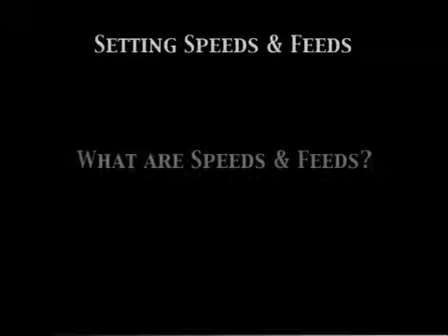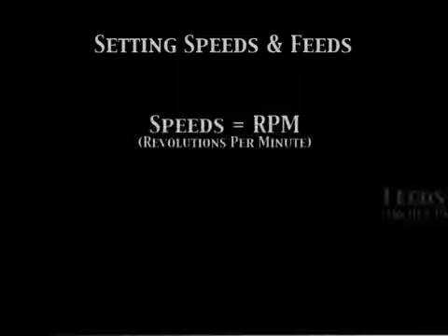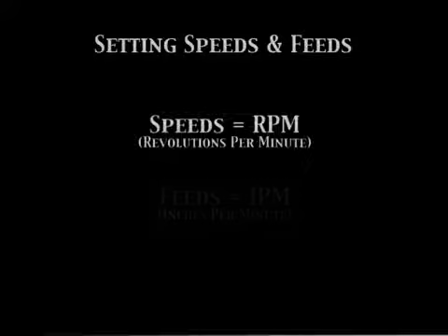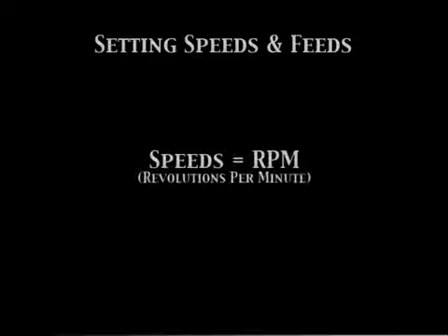What exactly are speeds and feeds? Speeds are the tool's revolutions per minute, or RPM. Feeds are the tool's linear or radial movement measured in inches per minute, or IPM. Let's look closer at figuring our RPM.